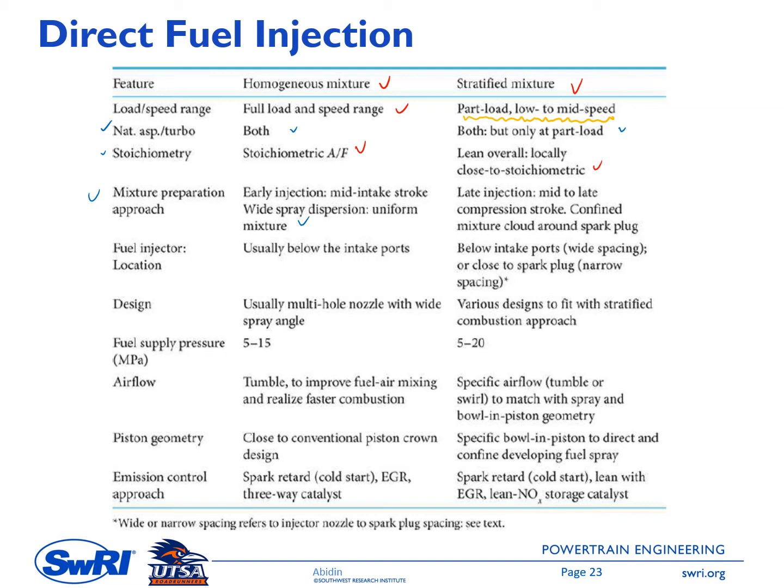Once we have a decent flame size, it doesn't matter if we have a lean mixture, because this flame should be strong enough, large enough, to have successful combustion throughout the chamber which has a lean mixture.